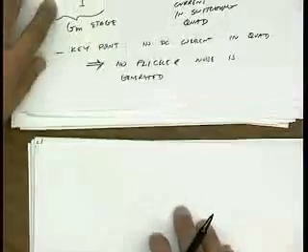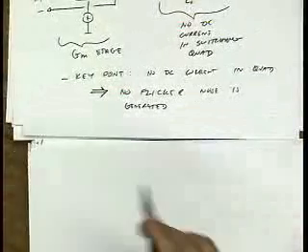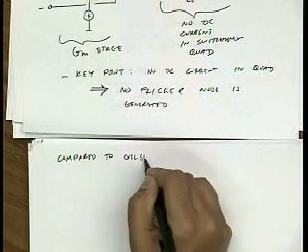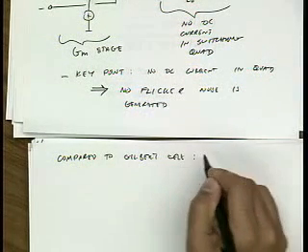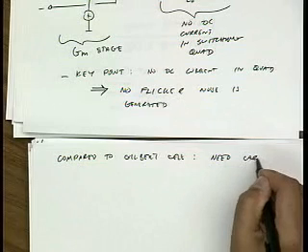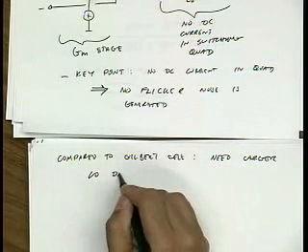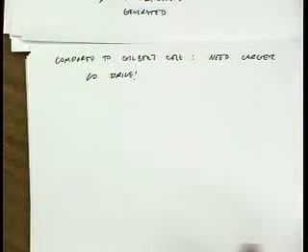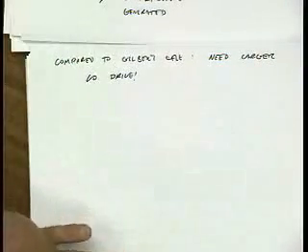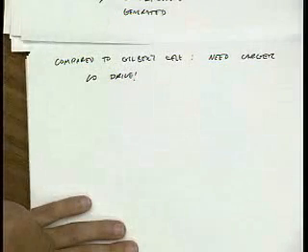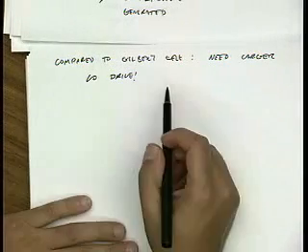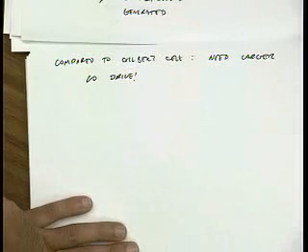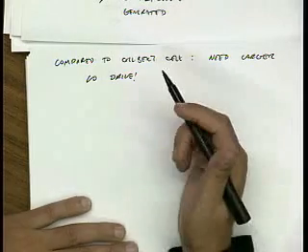Now, one of the disadvantages, let's say comparing it to a Gilbert cell, is that we need a much larger LO drive. That's because in a Gilbert cell mixer, the amplitude just needs to be large enough to switch currents back and forth, and all the devices can remain more or less in saturation. Here, we're actually completely switching the device off into cutoff and then switching it hard on in triode. So we need a larger LO swing to do that.